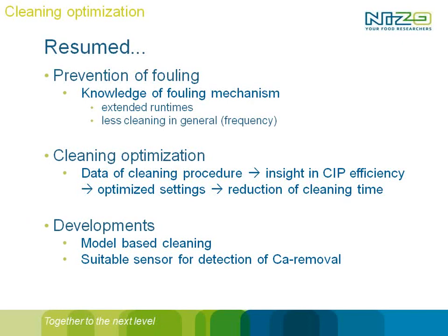Some new developments are model-based cleaning, the OptiCIP, which I showed, and well, we're still looking for the best calcium sensor, or the best sensor of calcium detection, to follow that one in line as well. But we have some troubles with finding a good one for really 24/7 industrial application without giving any problems. But these are developments within cleaning.